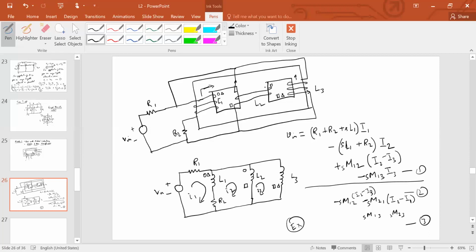Yeah. So what is the direction of the flux here? The direction of the flux is downwards. All right. So it is basically coming here and adding to this. What about this? If you now look at this, the way this current is flowing here. So give the current directions according to the source now. If this current is flowing through this, what is going to be this direction? The direction of the flux is actually this.